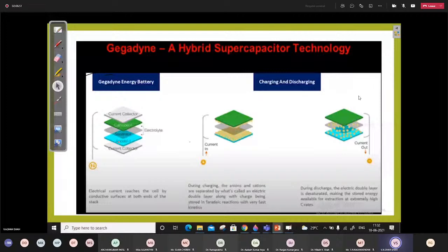So you need 17 of these 12-cell series connected strings, now 17 strings should be connected in parallel to get this. So you can see that the size of your battery becomes very huge, even though it demands an average power of only 1.143 kilowatt instead of 4.123 kilowatt.